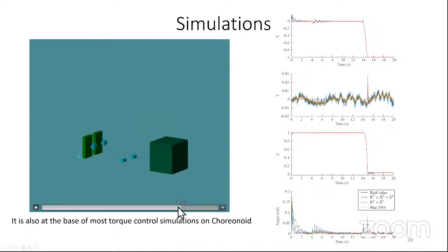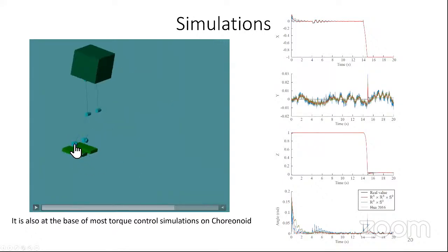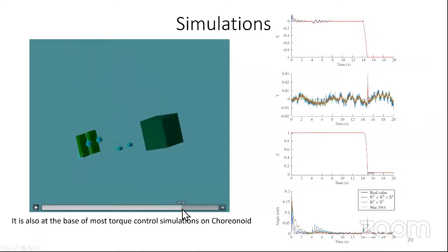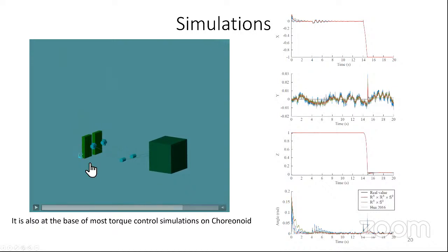So we just use the force sensor to get the ZMP, and with the ZMP we can rebuild the position of the fixed point. So of course it depends on this assumption. If I don't know the fixed point, or if it's wrong, or if the robot is slipping, it would be less precise, but the error would be filtered because this estimation is going through a complementary filter. So if there is a short slip, it will be filtered.